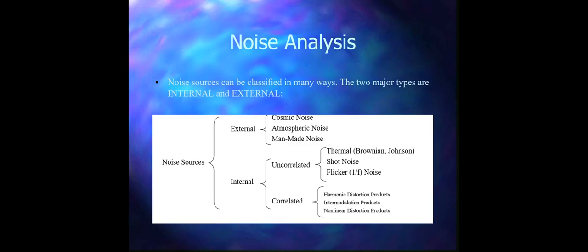Because a very large number of charges are all doing this at the same time, an AC noise current is produced, and this noise current is random, just like Johnson noise in the resistor we took as an example before. All frequencies except DC are present. The factors affecting shot noise are the DC current and the bandwidth.